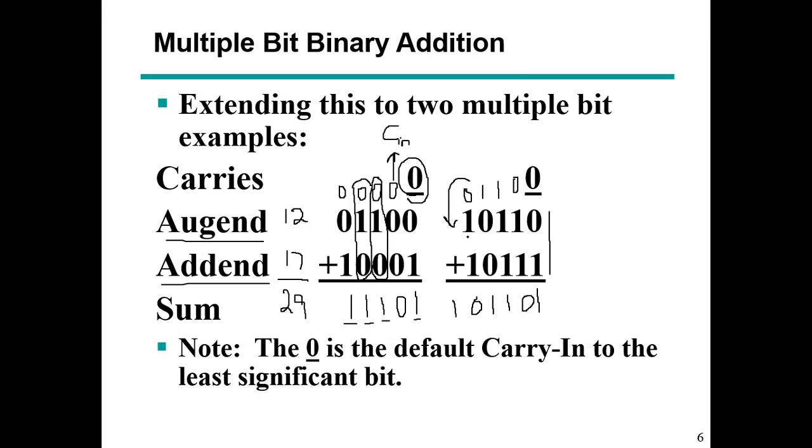So these two numbers are 5-bit numbers, and their sum has overflown. Their sum cannot be stored in 5 bits. Now which numbers are these in decimal? So let's practice our binary to decimal conversion. This is 16 plus 4, 20 plus 2, 22. This is 16 plus 4 plus 2, 22 plus 1, 23. Their sum would be 45.